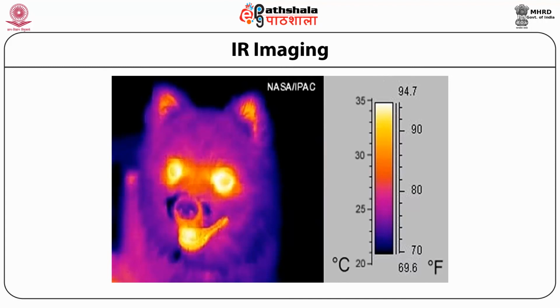The pyroelectric elements used in the devices are typically square plates with sides about a millimeter long and thickness of about 30 micrometers. Because the entire scene is focused onto the plate in thermal imaging, they have to be larger. Typically, squares of side about 1 centimeter, with thickness the same as for the simpler device.